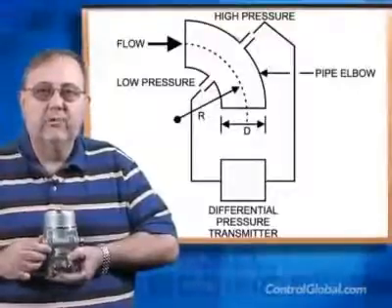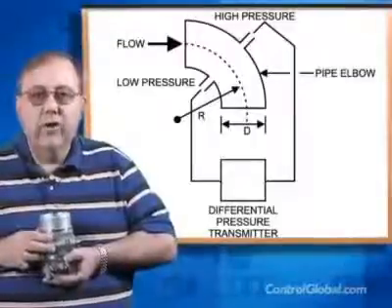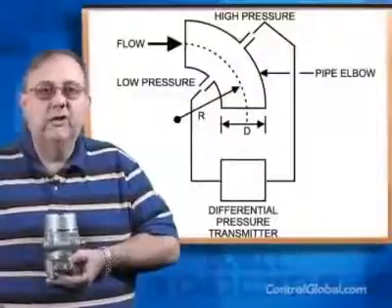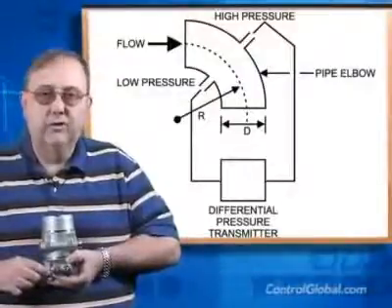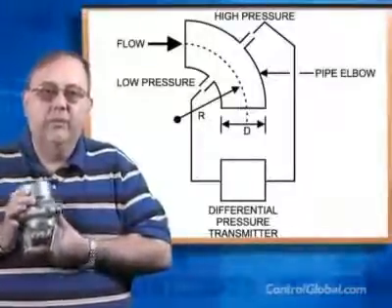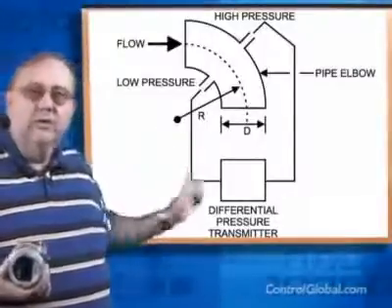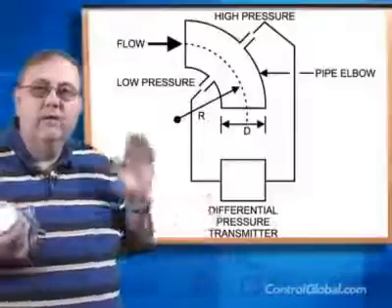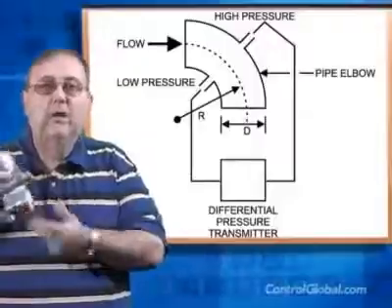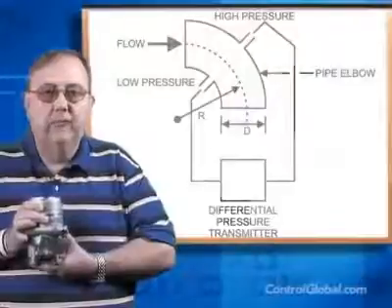Differential pressure transmitters have been designed using many technologies, including capacitance, differential transformer, force balance, piezoelectric, potentiometer, strain gauge, and vibrating wire, and many of these techniques are still in use. The performance of a differential pressure flow meter is defined by three things. The first is the accuracy and installation of the primary element. The second is the piping of the pressure lines from the primary element to the transmitter. And the third is the accuracy and quality of the differential pressure transmitter itself.